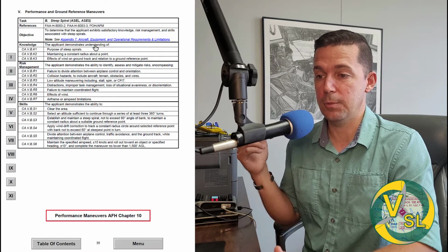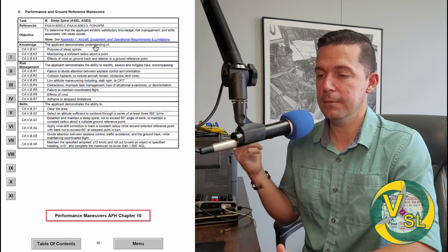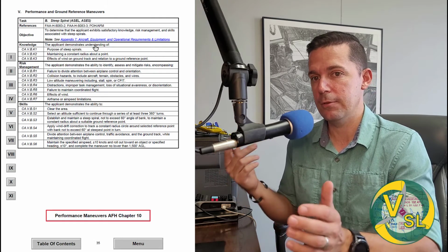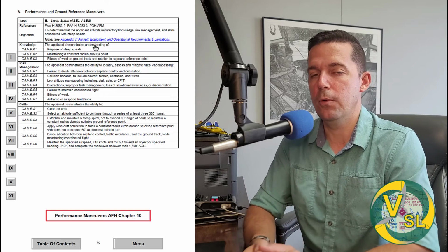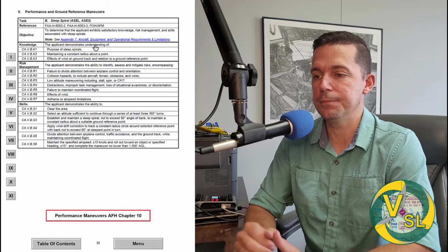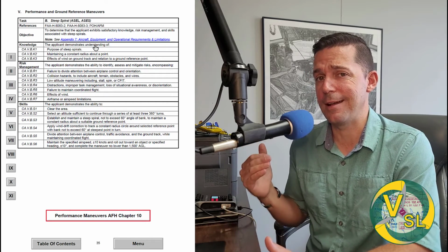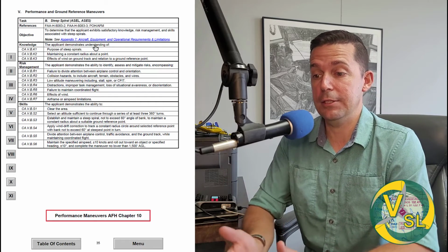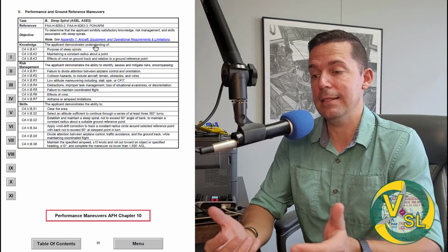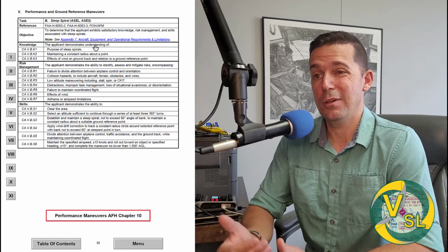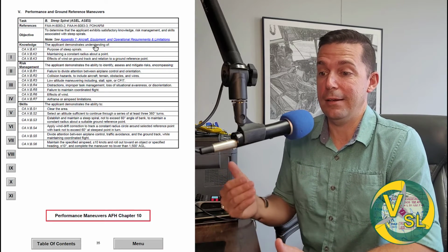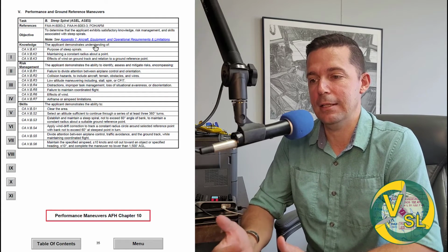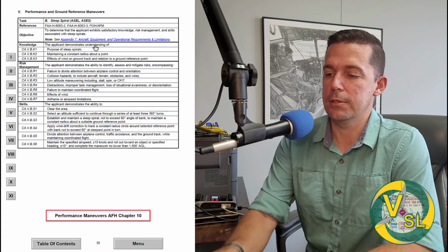This is great to practice over an airport that isn't very busy, and you can just spiral down. You get your 3 turns. That's a critical point, is 3 turns. That's probably where most people make an error on here, is they choose an altitude that's not high enough and they only get 2 turns. Well, the skill says specifically at least 3 turns. So err a little bit high, right? Because if you get 4 or you get 3.5, that's fine, but we need at least 3 turns.